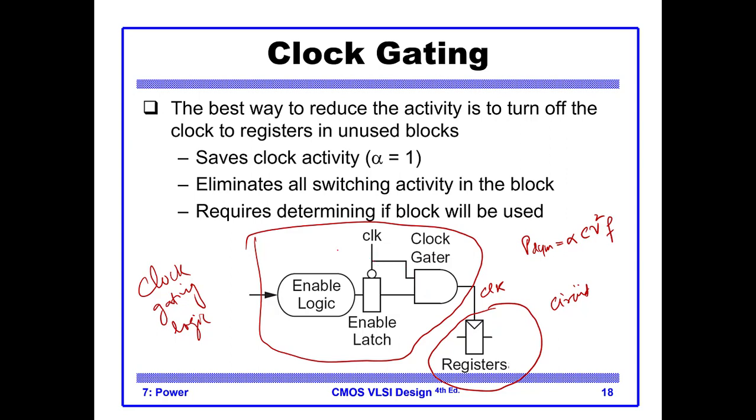One is your clock, which is coming from the crystal, and the other input is coming from user control logic. So when the user control logic is 1, the clock is considered to be passed, and when it is 0, the clock is 0. So when the clock is 0, there is no switching and your circuit consumes no power.